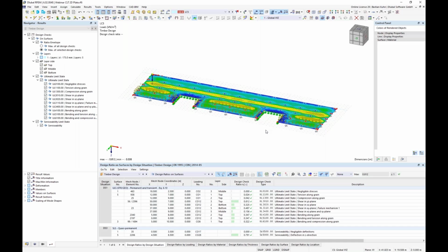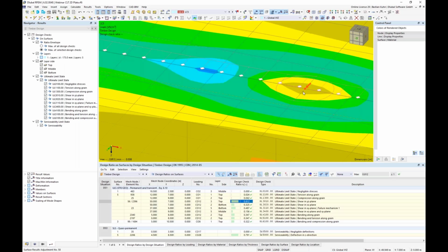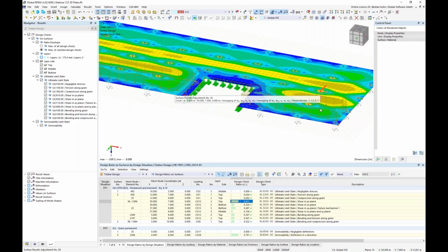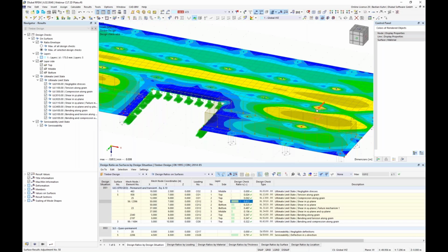And now we can take a look at the results and then just create a printout report and we are fine. Results good now. So the overloading of 1.1 is now changed into a loading of 0.8. Of course, you should make a finer mesh in here. If you look in here, you see that the span is just smoothing it about this area. But in general, that's how it can be done, or how to regard the punching in here and how to avoid this overloading.